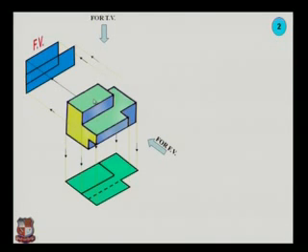We will take the orthographic projection by considering the projectors from the corner points. This is the first rectangle. It is the orthographic projection of this part of the 3D object, and it is the base. This base is similar to the 3D object as we can see from the top view.